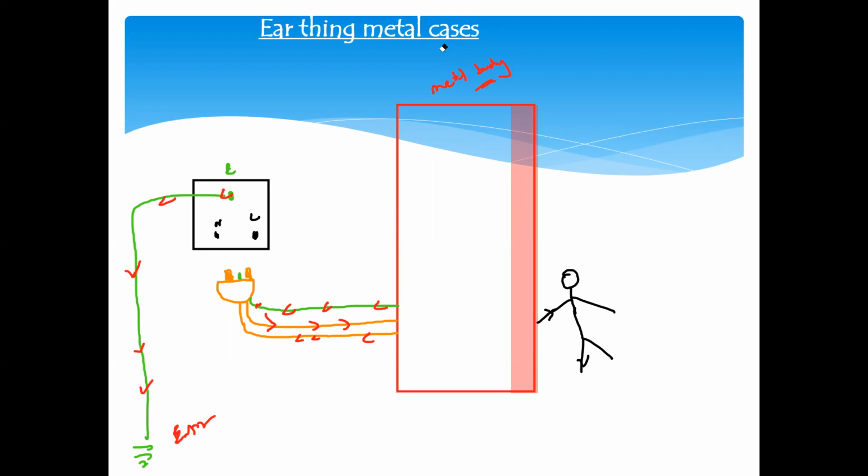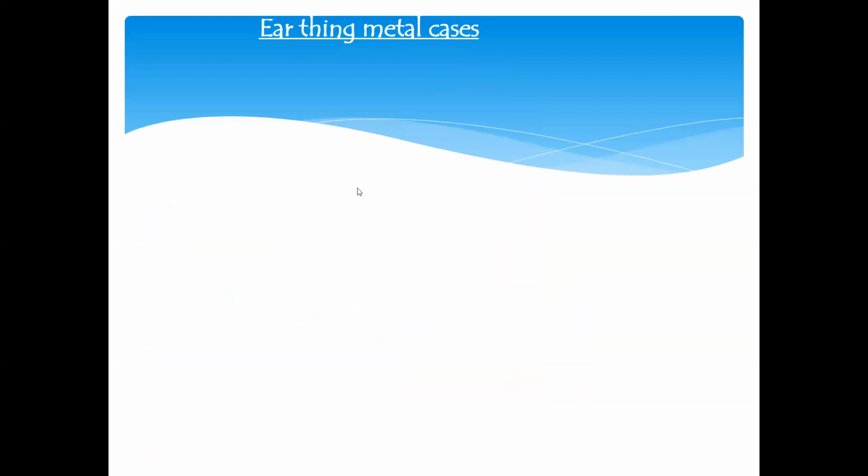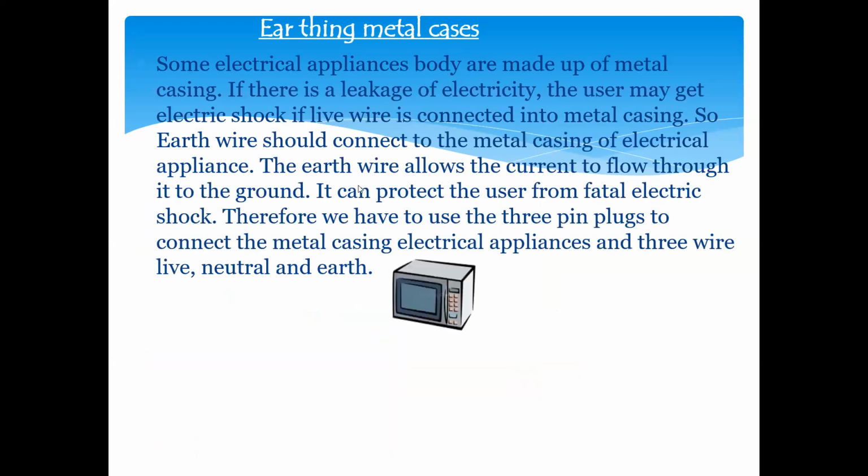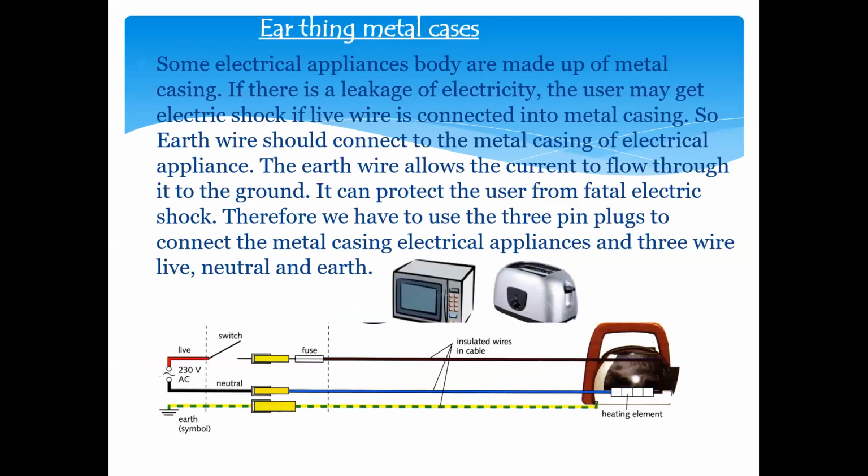But with laptop chargers, you will find 3 pin plugs, and the third pin is made of metal. Because the laptop has a metallic body that can conduct electricity, sometimes when you touch the metallic body, you might get an electric shock. So to remove that extra current, it is connected to an earthing wire. Is the concept of earthing and the use of the earthing wire clear?